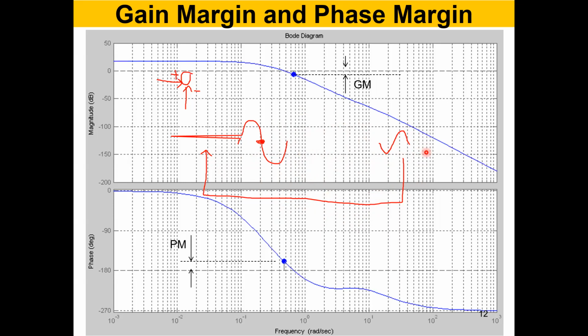That is good news. The system is safe even though the signal you are feeding back is 180 degrees out of phase, because the gain is less than unity. Every loop, the gain reduces. But how much?